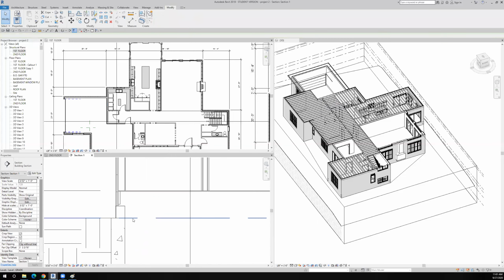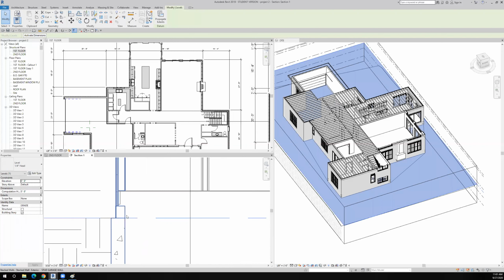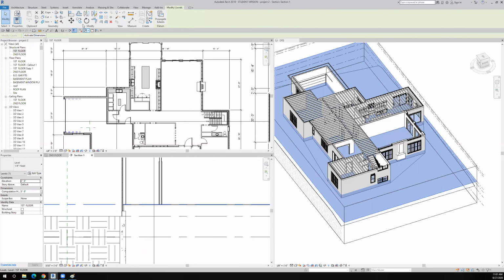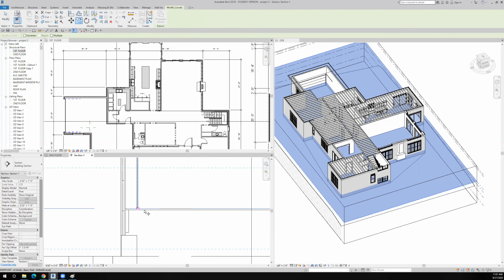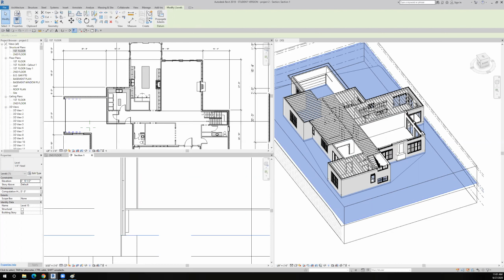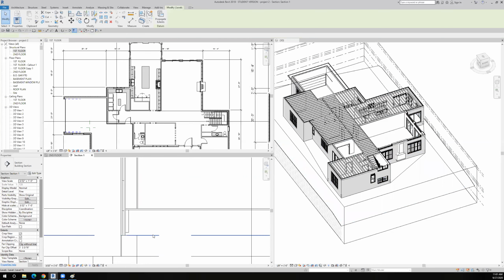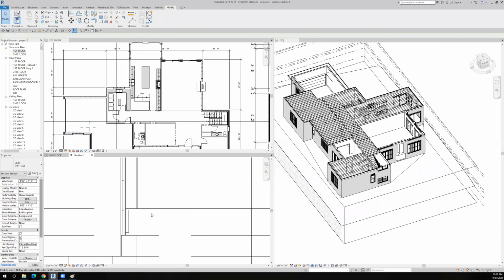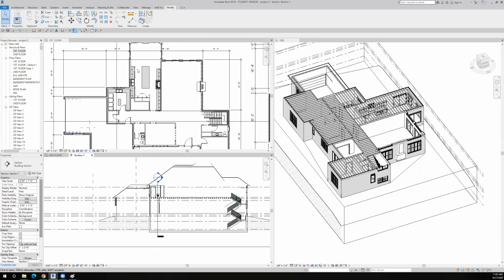Anyway, I want to put in a steel beam now, and I know where it is relative to the sections, but I'm going to copy this guy. That's the grade. So I'm going to copy one of the levels. So I'll just copy this level, and I'm going to copy it down from here down to here, and I'm going to rename it. I'm going to rename that level top of steel beam. So instead of level 15, I could scroll out and click on it on the side and change it, but I'll just change it right here. So caps are always good. TO steel beam. So now I have a level that I can assign my steel beams to.